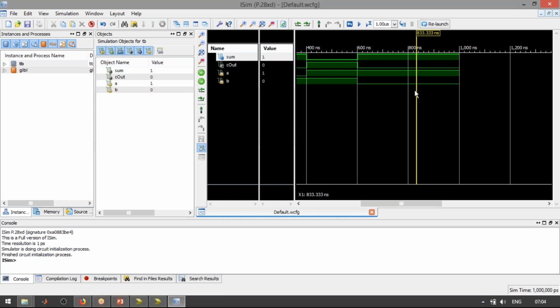So whenever we are disconnecting the wire, still the value is present inside the register. That means the previous value is retained there. But in the case of a wire, if you are terminating that element or net, then it automatically disconnects from the terminal. So there is no information present in there. So maybe it is in a condition of X, that means don't care condition, or in a high impedance state.